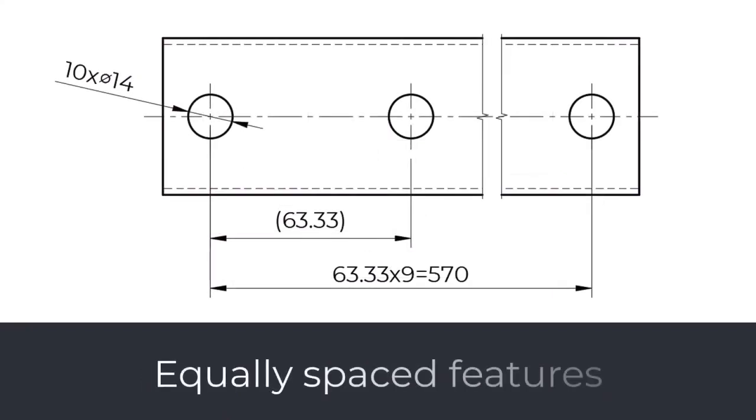Equally spaced features. When features are equally spaced, we can simplify dimensioning one and write how many times it is repeated.